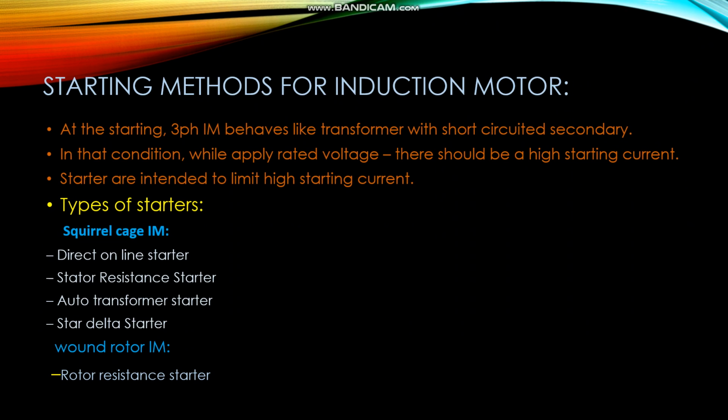Starting method for induction motor. Why do we need a starter? At starting, the three-phase induction motor behaves like a transformer with a short-circuited secondary. In that condition, while applying the rated voltage, the starting current will be very high. Starters are intended to limit the high starting current.